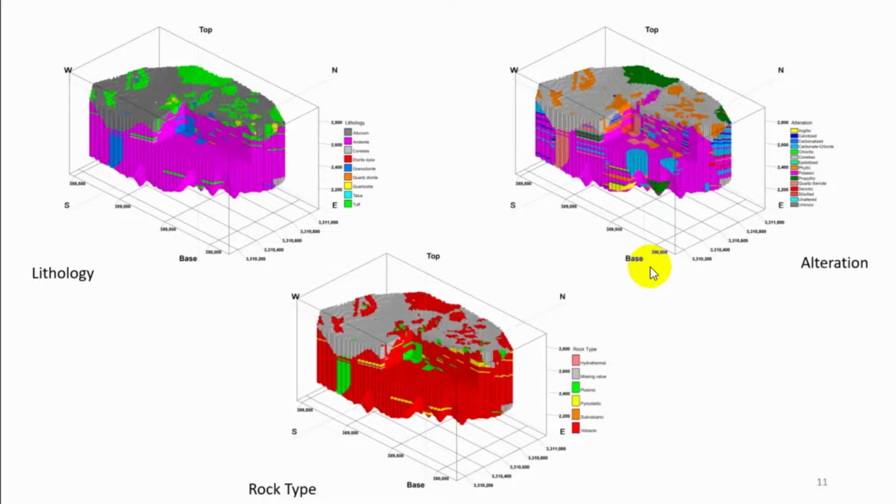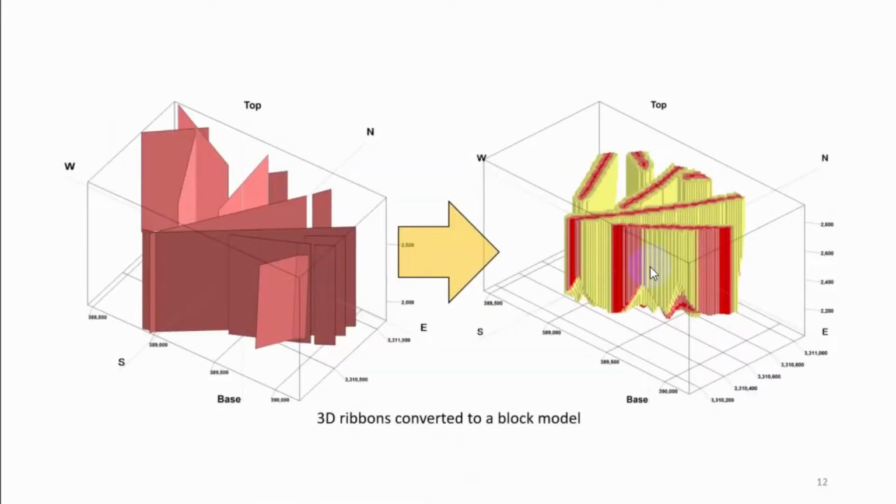And we use closest point interpolation method to create these solid models. In addition to these geological models, we use the structural data, mostly based on our observations from the surface. And we created these block models using the fault surfaces. We also created 2 buffer zones around the fault blocks with a radius of 25 and 50 meters. And these block models of faults have also been used as input evidential models.